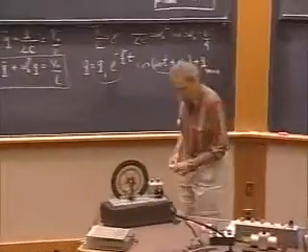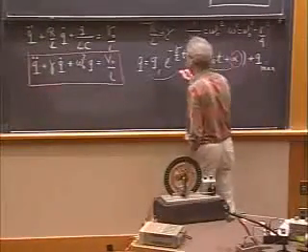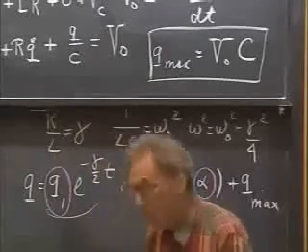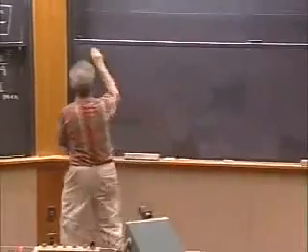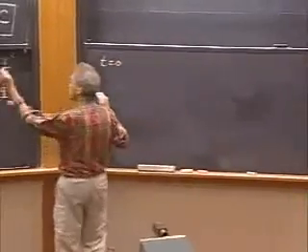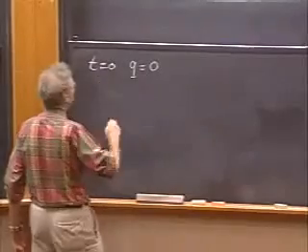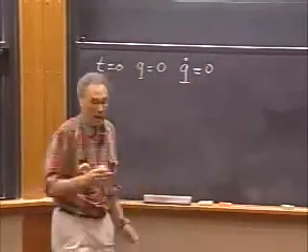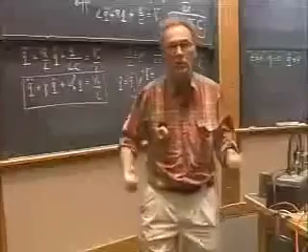You now have to solve, depending upon your initial conditions, for alpha, and you have to solve for Q1. So that means you have to know your initial conditions. And the initial conditions of this problem, for instance, would be that at t equals 0, when I throw the switch, there is no charge on the capacitor. That is one way I could do it. And there is no current flowing. That could be my initial condition. Not the only one possible, but that is a possible initial condition.